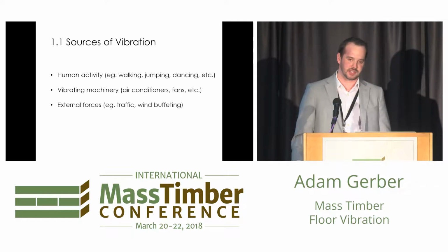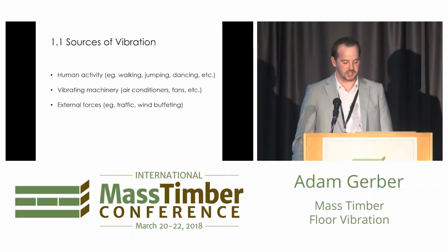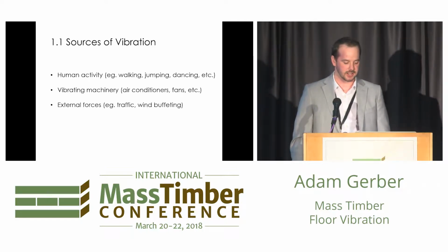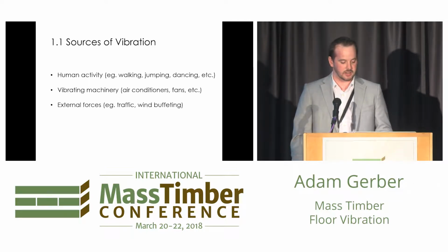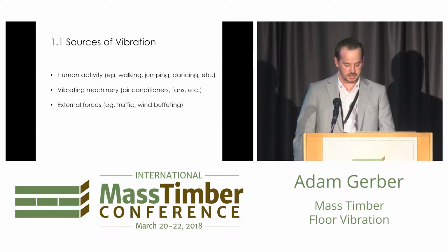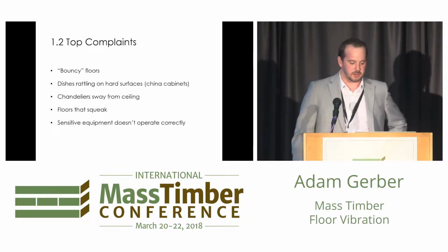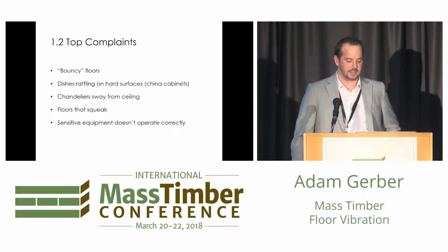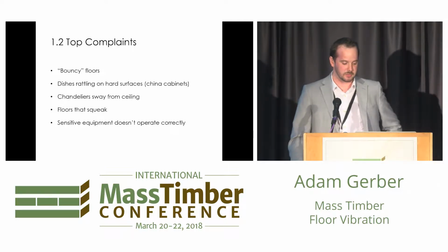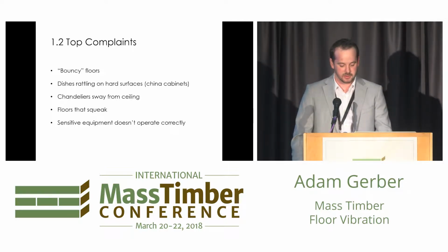So briefly, some sources of vibration: human activity, things like walking, jumping, dancing, potentially vibrating machinery, air conditioners, fans, anything with rotating parts if it's not properly isolated, and external forces such as traffic, wind buffeting, etc. We're really going to focus on walking-induced vibrations today. Some of the top complaints that we get: bouncy floors, dishes rattling in cabinets. If you have a bouncy floor in the roof, sometimes fixtures will start swinging from the ceiling. That can be pretty uncomfortable for the people below. Floors that squeak, sensitive equipment.